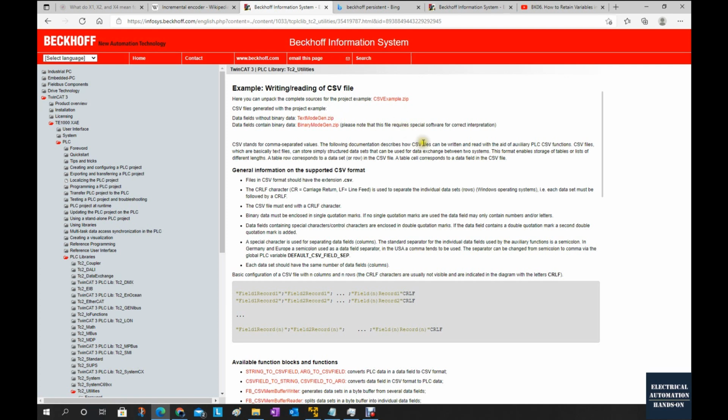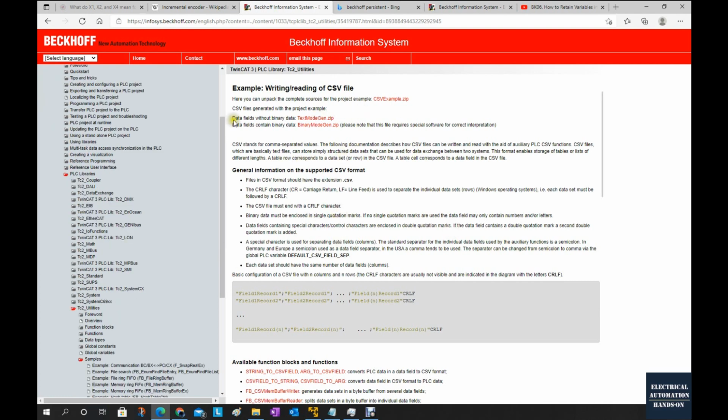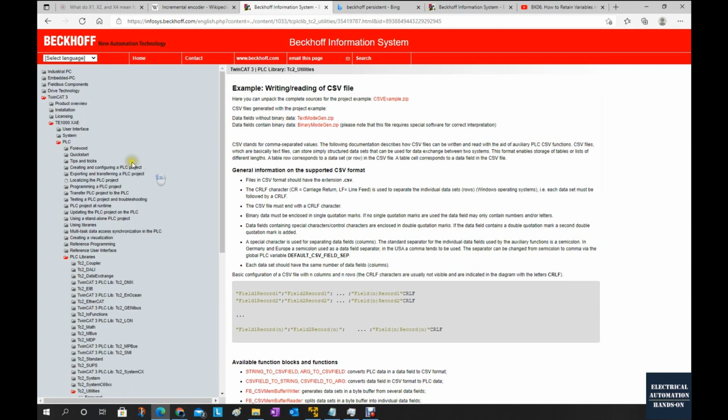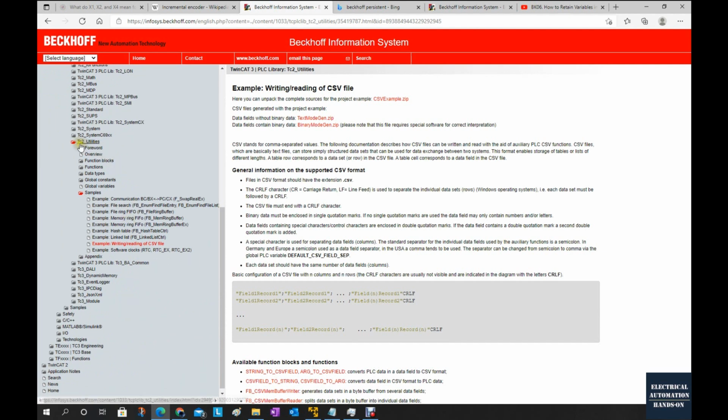In this video, I will show how we can implement this. To implement CSV writing and reading, there is no standard function block. Alternatively, Beckhoff provides an example. To find this example, we can go to the Beckhoff Information System and find TwinCAT 3, TE1000 XAE, PLC libraries. Go down, find TC2 Utilities, and click Samples. Under this sample, it provides one demo project, a PLC archive project, named writing and reading.